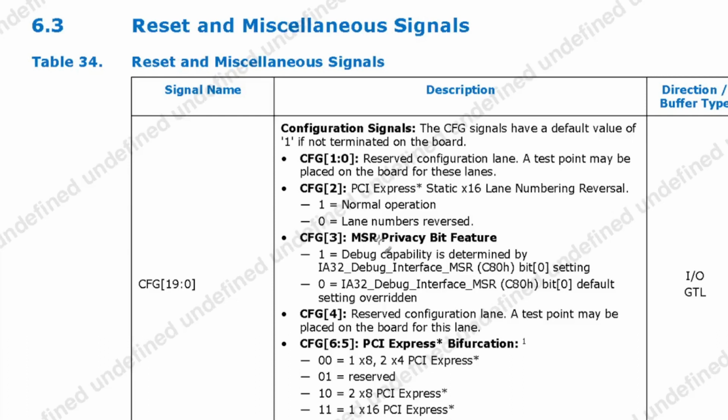This wraps up the content for this video, and as shown here, PCIe bifurcation is also possible to configure with the same config resistor overrides on the motherboard. If there is any interest in showing how this can be done on motherboards which do not support it explicitly as a BIOS option, then I may make another video, but it is generally the same method of modifying resistors shown here.